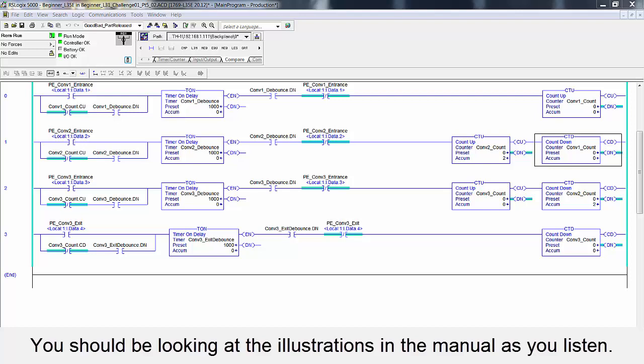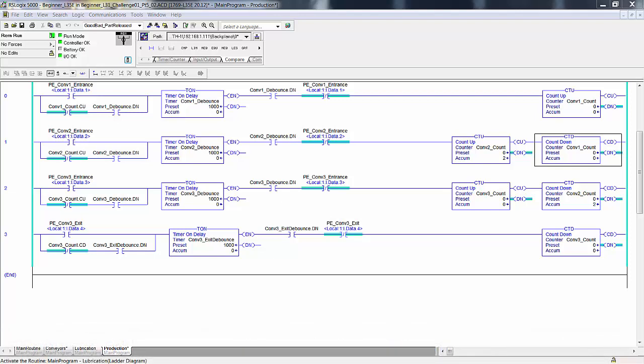Meaning that once in step 3 you have a carton blocking 1 PE, the only difference between step 3 and step 4 is that if the motor is running, you are assuming the carton is moving through the photo eye continually. So carton in step 3, it arrives and blocks the photo eye. If you decide to run the conveyor, then in step 4, you have to decide whether to keep running it or to stop. Now obviously in our code we're looking for the trailing edge of the carton to stop. But still, you need to think through every single aspect of what's going on in this very, very simple process.